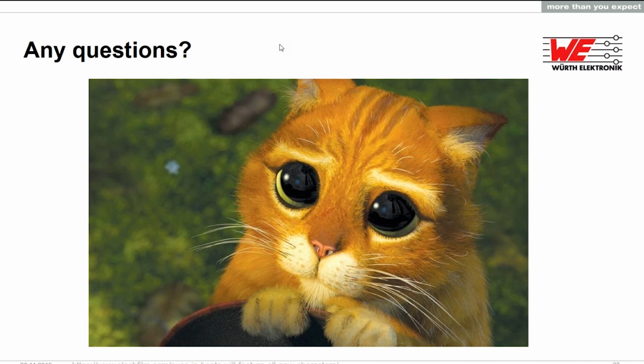And as I see right now, we're only having one last question. Will the old ferrites be measured again with the new setup, and do you update the old data sheets? We do have a plan next year to measure all the ferrites, all chip bead multi-layer ferrites, so that we can update the data sheet to the new measurement setup for up to 8 gigahertz.